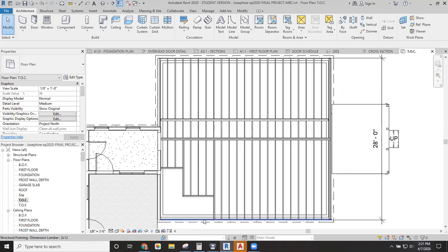And for your I-joists, Nick, I don't know if you need to double up the I-joists in your scenario or if they would just be single, but if you look at that PDF, there's a lot of pictures that show you how the framing is configured in different scenarios. There's a lot of good 3D pictures that show you those connections. And in some places they would use just a laminated board instead of headers. So check that out if you're using the I-joist for your framing, just so that you know, you're not detailing that.